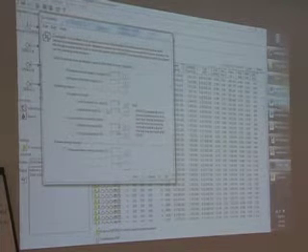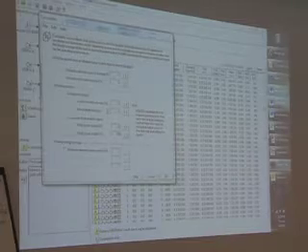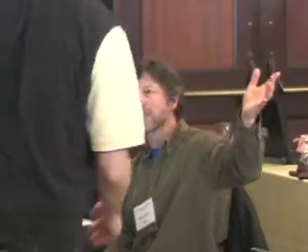Yeah. I'm not a system operator. I've been working with utilities on modeling and dealing with their spinning reserve requirements here in the rail belt, which is different than kind of the grid situation. But when they call spinning reserve, they base that on the single largest unit that's running. And so if you lose your biggest gas turbine, let's say, which is what typically it is in the rail belt, you have to have something else to pick that up instantly.